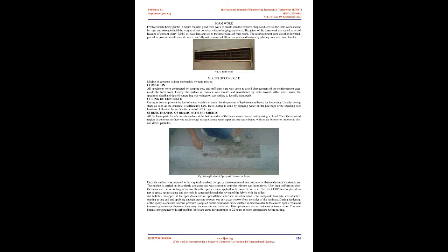Disadvantages. The main disadvantage of externally strengthening structures with fiber composite materials is the risk of fire, vandalism, or accidental damage, unless the strengthening is protected. A particular concern for bridges over roads is the risk of soffit reinforcement being hit by overheight vehicles. However, strengthening using plates is generally provided to carry additional live load, and the ability of the unstrengthened structure to carry its own self-weight is unimpaired.